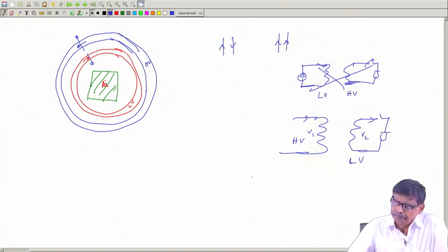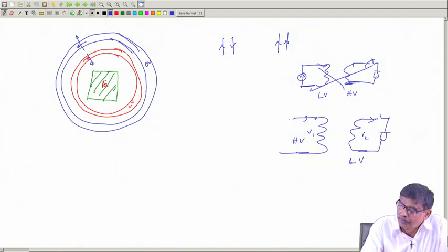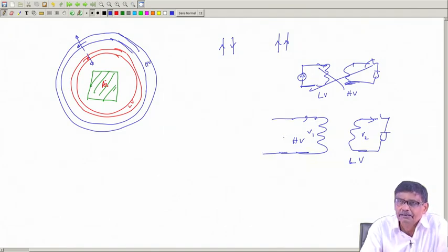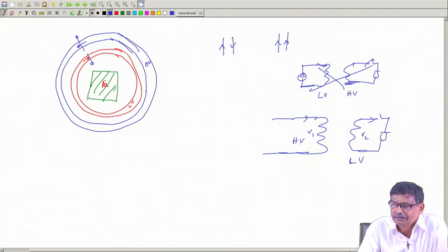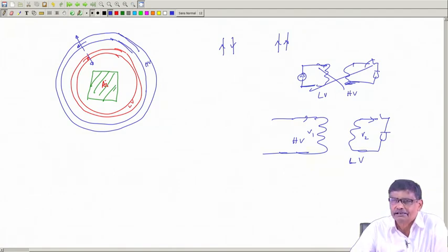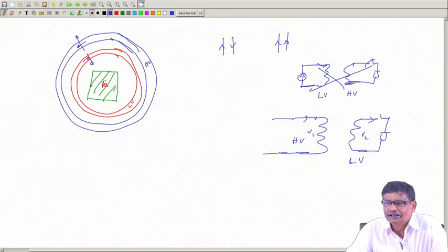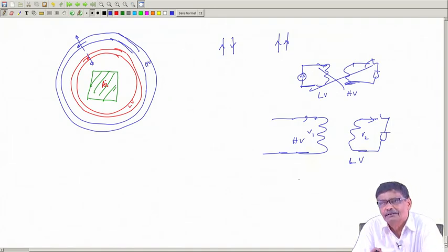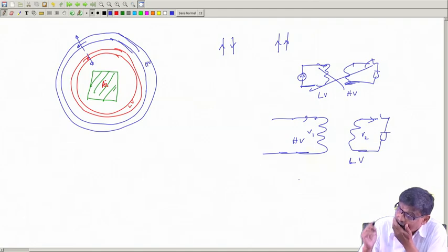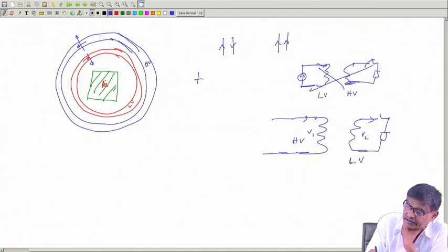And suppose you want to restore the voltage back, you cannot do anything here. Two ways you can do. One thing is you increase the supply voltage a bit. The supply voltage whatever is coming, that voltage you increase, so that it may compensate that. But that is not an option left to you. Supply voltage whatever is coming, you cannot do anything. So, what can be done is, some transformers are provided with tap changers.